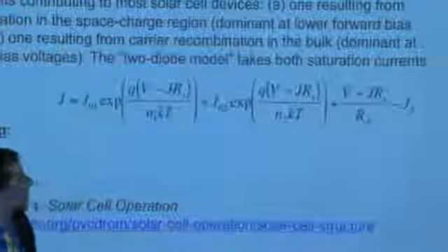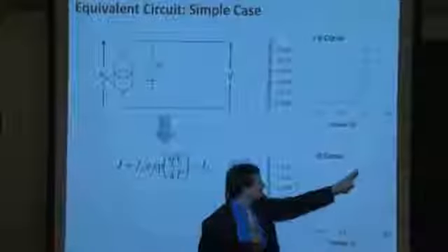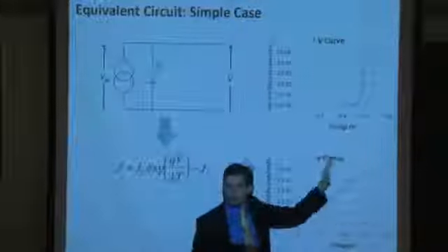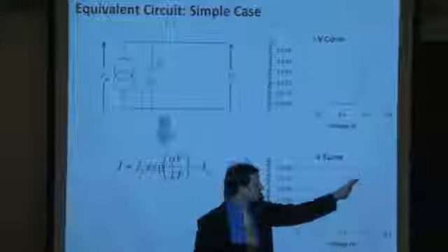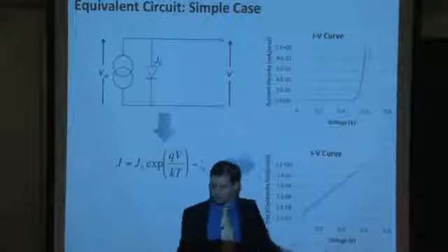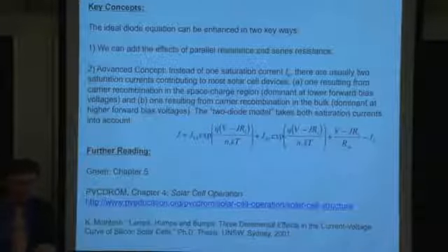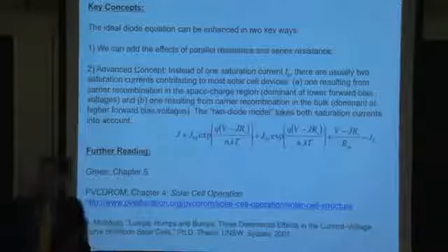Another thing you might see pop up is this ideality factor showing up right down here. The ideality factor is a slope factor. What that means is, here, if we go back to this, if you change your ideality factor, you're changing the slope in log scale. It'd still be a straight line, but if your ideality factor increases, you would get something like this. If it decreases, the slope would increase, right? Because you have the equation dependent on 1 over this parameter. Okay. So the ideality factor is important as well because it indicates the type of recombination mechanism that's driving the current inside of that region of the device. And if anybody ever comes across this in the research, come talk to me.